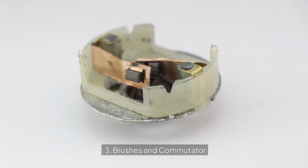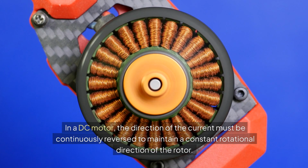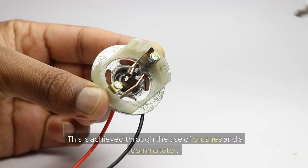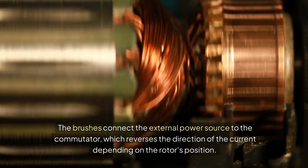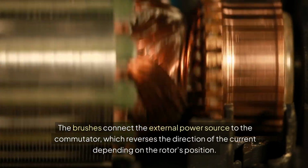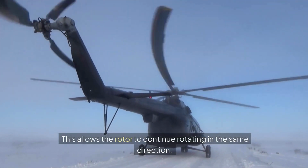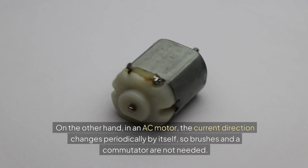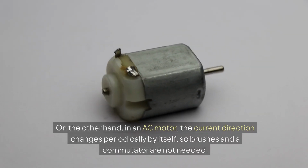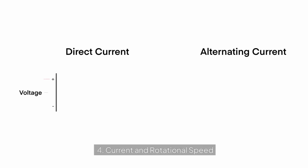3. Brushes and commutator. In a DC motor, the direction of the current must be continuously reversed to maintain a constant rotational direction of the rotor. This is achieved through the use of brushes and a commutator. The brushes connect the external power source to the commutator, which reverses the direction of the current depending on the rotor's position. This allows the rotor to continue rotating in the same direction. On the other hand, in an AC motor, the current direction changes periodically by itself, so brushes and a commutator are not needed.